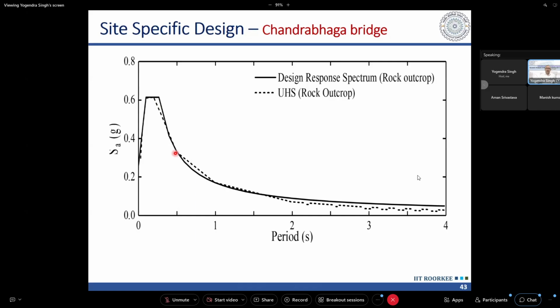Here, at different periods, different earthquakes govern. For example, at longer periods, larger earthquakes occurring away from the site are going to govern, whereas in short periods, those sources which are nearby to the site are going to govern. So different sources govern different regions of this response spectrum. This response spectrum is not given by one earthquake, rather it represents a set of earthquakes, all possible scenarios which we identified in the previous slide.